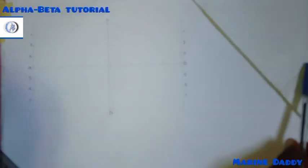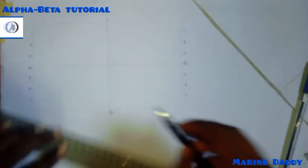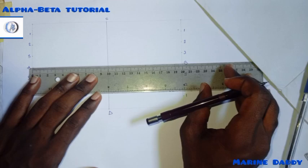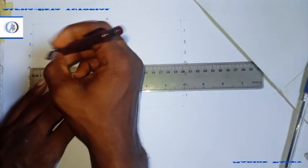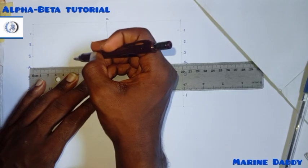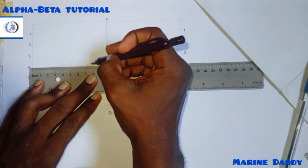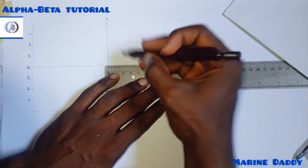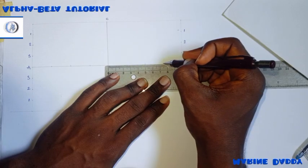After doing that, this line at the center, not the top and the bottom, you are going to divide into 8 also. From here to here is 20, according to what was given to us. When you divide it into 8 equal parts, we'll have 2.5. So 2.5, 2.5, 2.5. Come to this side again and start again. 2.5, 2.5, 2.5, like that.